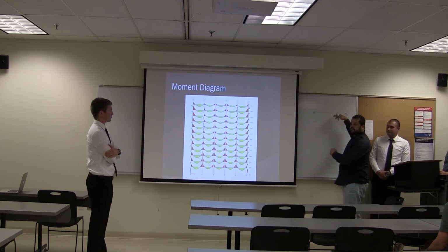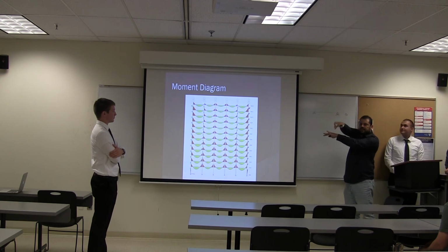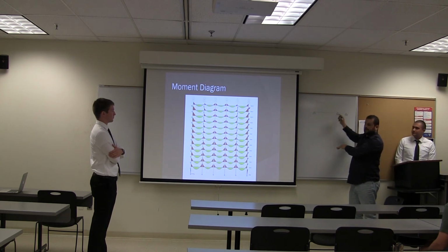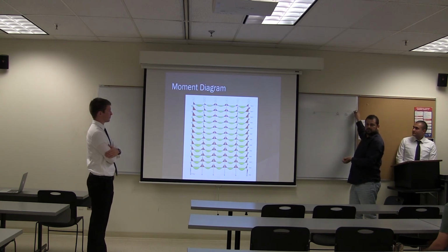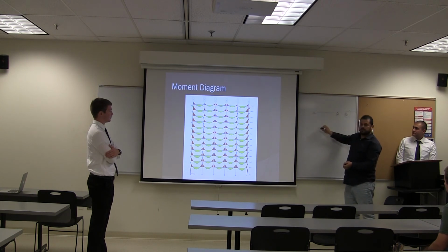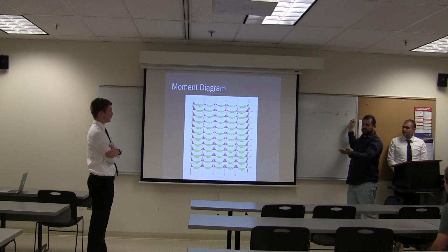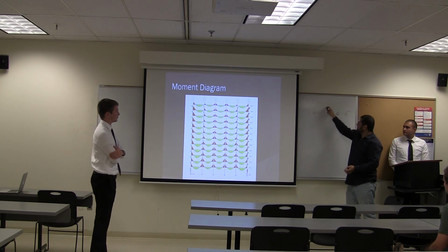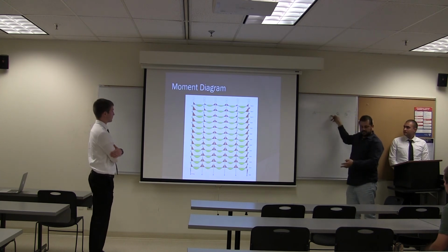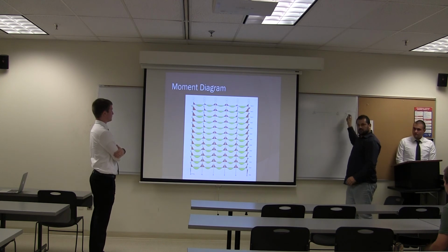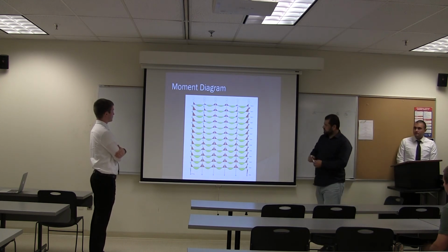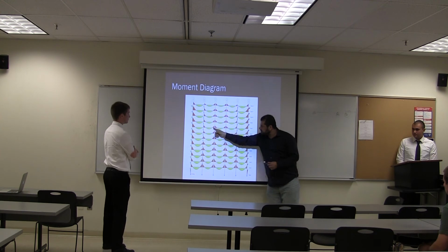This is a roller. It means it's not two segments. The beam is sitting on the support, so continuous over this. How is it going to be continuous over there unless you overhang it? In your case, you fix this. If you fix it, you develop a moment. If it's pin or roller at the end, no moment. But if there is an internal roller, there is a negative moment. If this is negative, or like that, like what I told you. See? So it's continuous over this column.